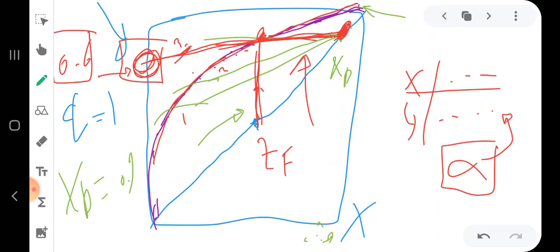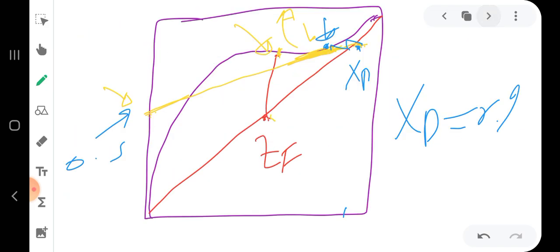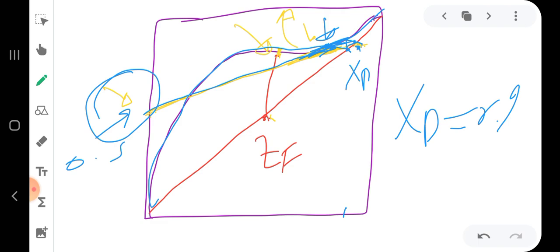If the equilibrium curve is good, like an x-y curve, we only draw a line that intersects the q line and the equilibrium curve, and then take the intercept to determine the r minimum. In the other situation, if we have this bad equilibrium curve, it is enough to only touch the equilibrium curve to determine the r minimum value at this intercept. So these are the two situations.